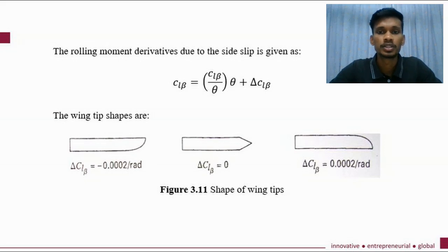The direction of relative airflow increases the effective angle of attack of the wing into wind and decreases the effective angle of attack of the wing out of the wind, tending to decrease the rolling moment. Therefore, a high wing position usually requires no geometric dihedral. In our case, the RC aircraft uses a high wing and there is no dihedral angle.